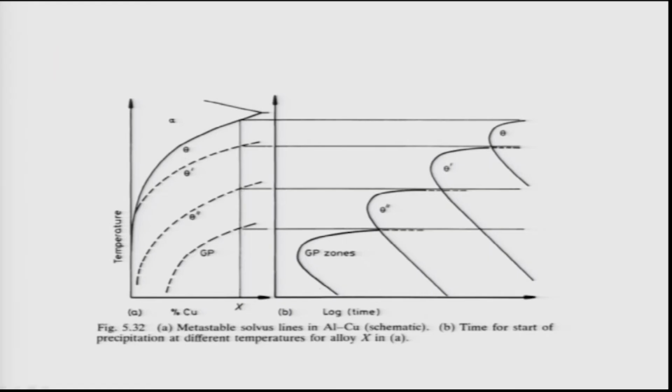Now we can have nucleation and growth kinetics built into that, and these curves are obtained like that. Obviously this looks like a Johnson-Mehl equation which is available for the steels. Why? Because if you look at any transformation, the transformation rate, if I plot temperature versus time, will be maximum at some intermediate temperature; at higher temperature it will be lower, and at lower temperature it will be lower. This is mainly because at high temperatures the driving force available is low. Therefore nucleation and growth rates are low.